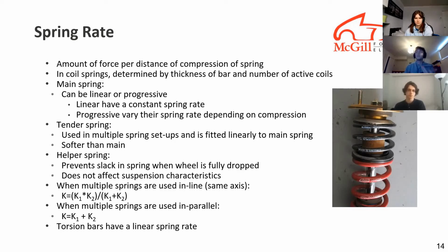And depending on how the springs are fitted together, whether it's in line or in parallel, it will affect differently how the spring rate will be affected. Torsion bars, on the other hand, will have a linear spring rate all the time.